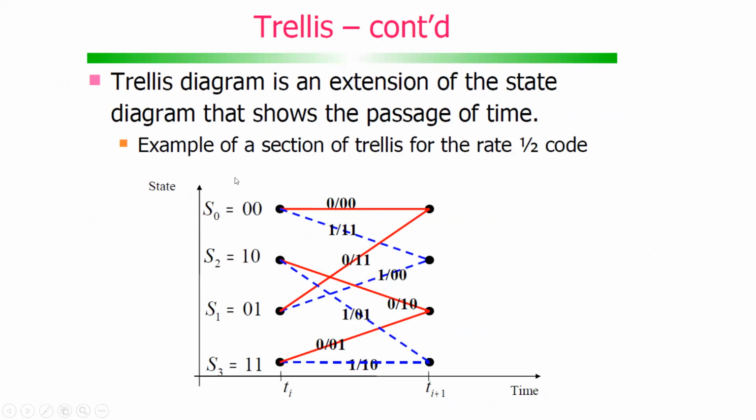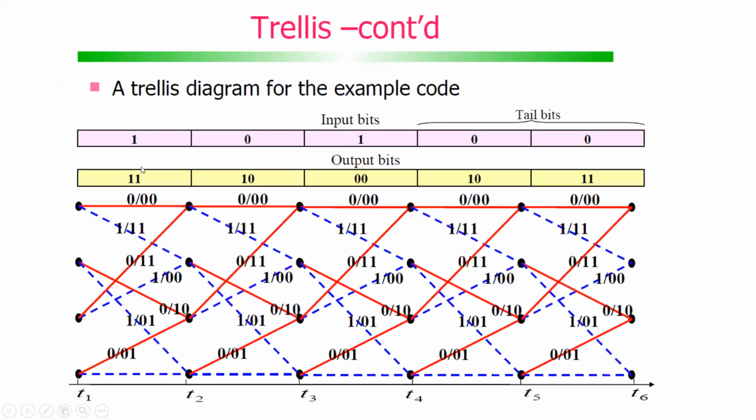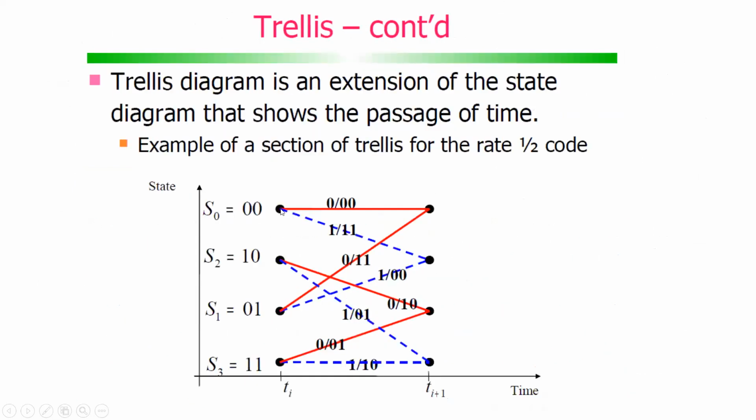All right. So let's look at the states. How many states are possible? 4 states are possible: 0 0, 1 0, 0 1, and 1 1. Now, let me come to this diagram. To draw the trellis diagram, to start with, first make 4 dots. Black, black, and black. 4 dots are made, and these dots are represented with the states 0 0, 1 0, 0 1, 1 1.